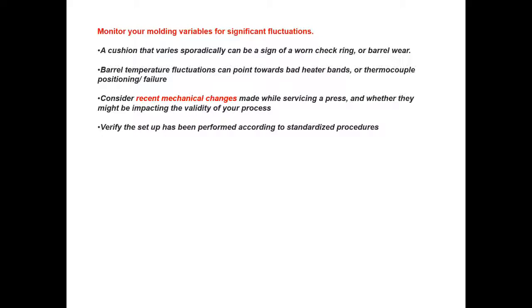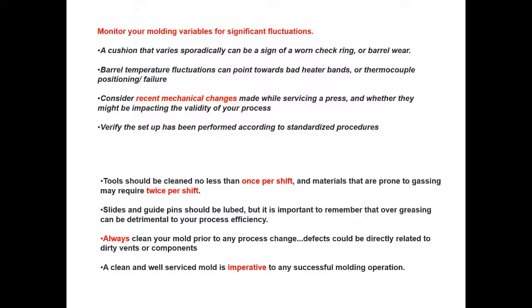In addition, you're going to want to verify that the setup has been performed according to standardized procedures. This quite often in startup is going to be one of the first things you want to check. You want to make sure that the setup was completed properly. In addition, you're also going to want to make sure that your tools are cleaned properly, no less than once per shift, and materials such as nylon that are prone to gassing may require twice per shift.